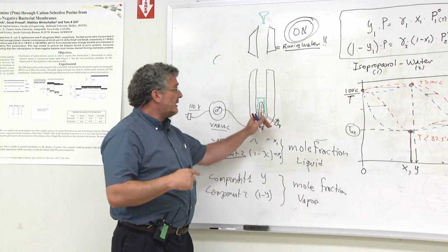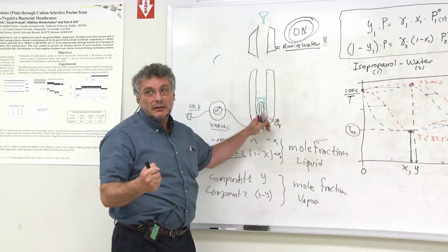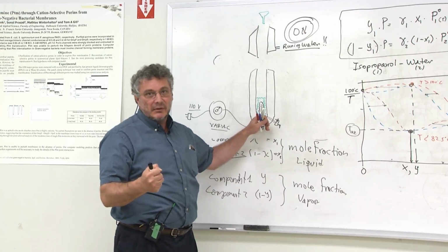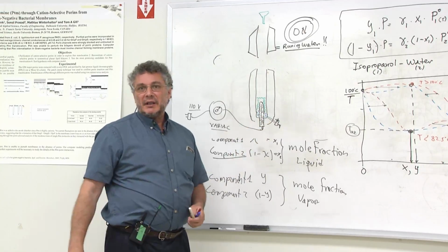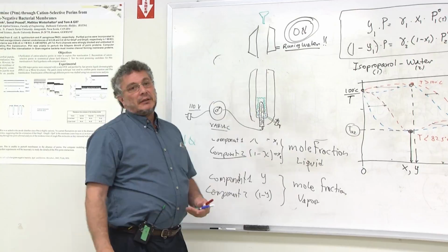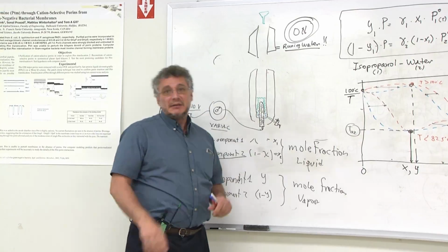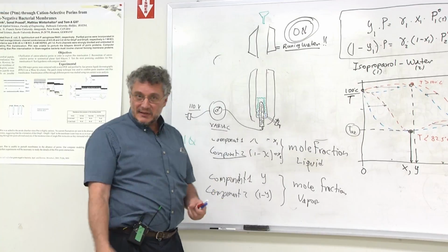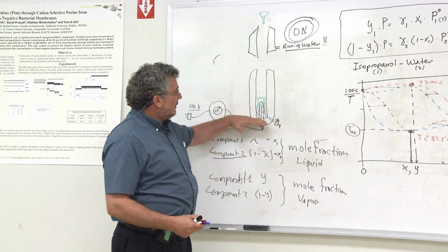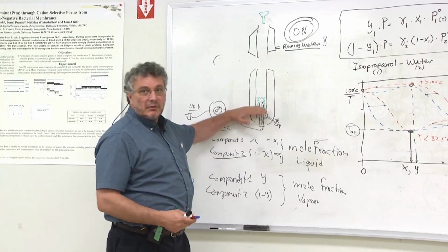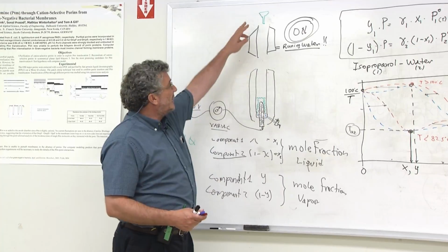As that happens, this glass will be cooled down almost instantly. It might crack, and if so happens, the isopropanol, now a mixture of vapor and liquid, will be in contact with a very high temperature element, and an explosion may ensue. It has never happened, but it is a possible scenario. So please make sure that the element is always cooled down before you apply the next sample.